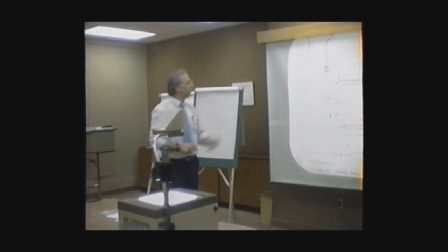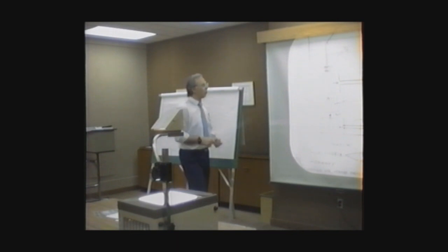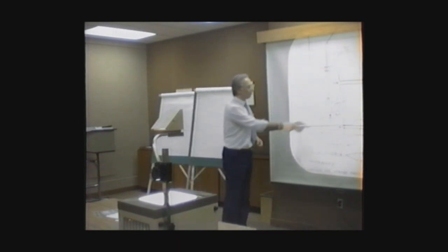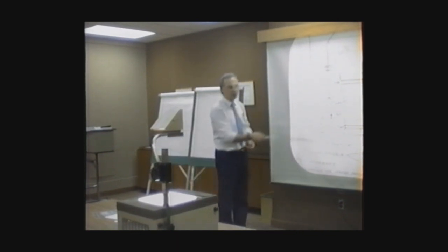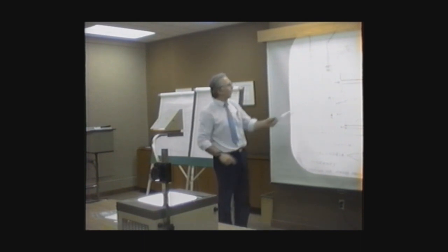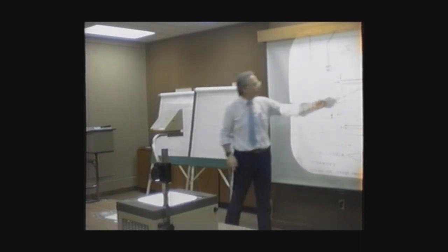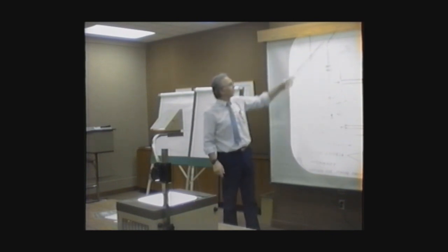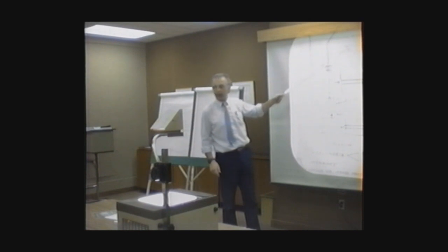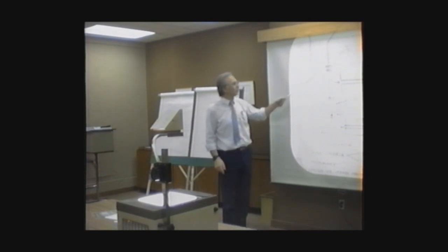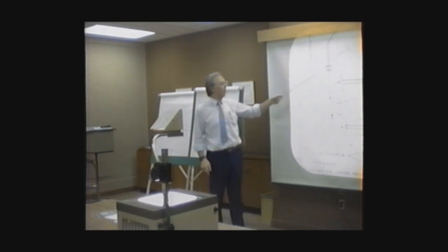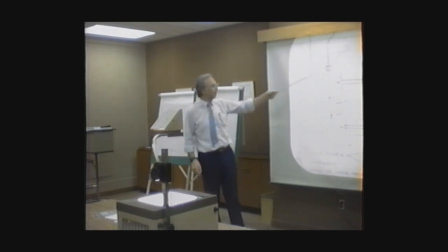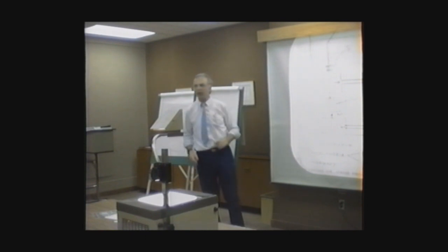The reactor is an open pool structure which has a plenum with a coolant, which is light water going through the chimney, through the pump, through the heat exchanger. There is a control mechanism which is magnetically coupled, and in case of shutdown, we just cut the power to the coil here, and because of the force of gravity, the rod falls freely into the core.